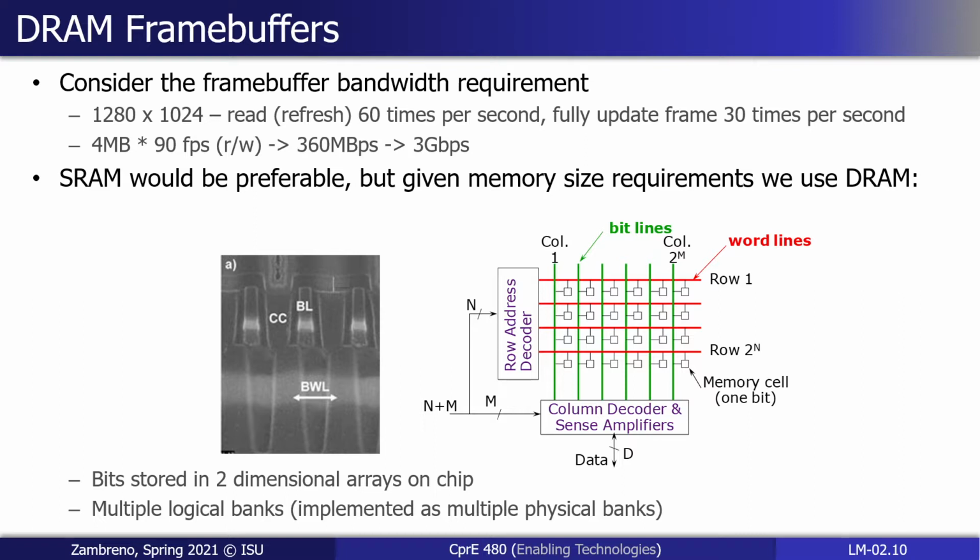More is better. And as we do talk about when you take 381, ideally we can make use of SRAM, where the fundamental technology is much faster than DRAM, but it's also much less dense. We can fit much less of it on chip at a given time. So while your SRAM sizes tend to be measured in kilobytes to small low-digit megabytes, you can certainly get your DRAM into the gigabyte range relatively easily nowadays.